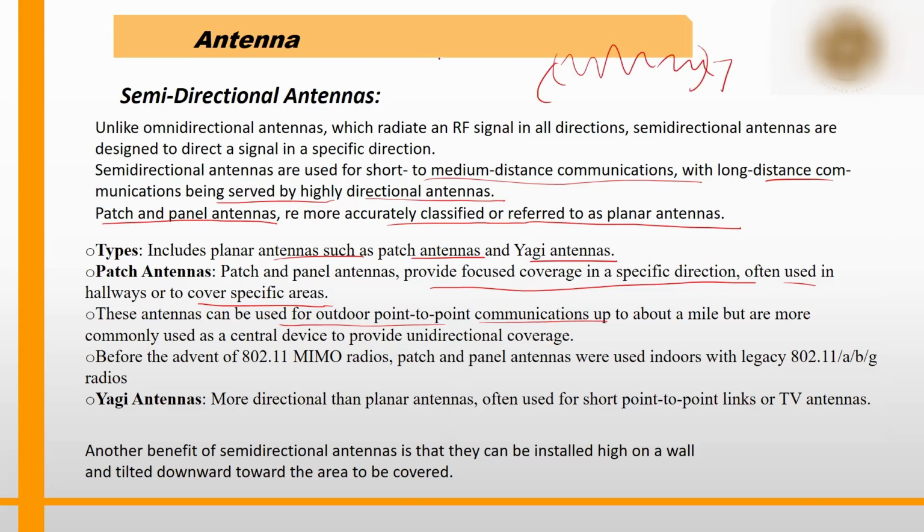But in our offices, we are going to use semi-directional antennas, that is, focusing in a single direction, that is point to multi-point, like multiple users. And in the semi-directional antennas, we have patch antenna, panel antenna. They are specifically called planar antennas. And then we have the Yagi antenna. Okay, that is also one type of antenna.